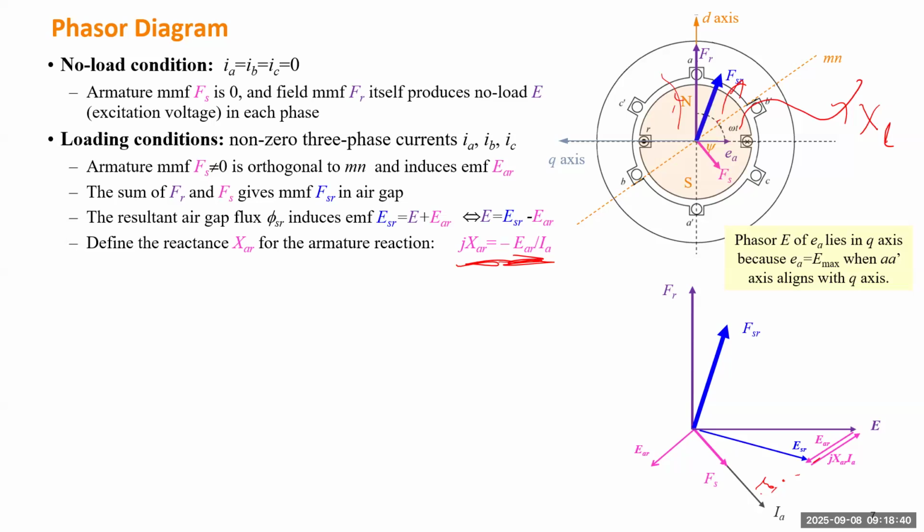Which means finally, if we connect the generator to a system, we cannot get this voltage, because this is the inside voltage, like the inside voltage of a DC battery, right? If we use the battery as an analogy, this is like the terminal voltage of an ideal generator without leakage flux, without resistance. But if it has some resistance and leakage flux, whatever voltage we get outside of the generator is not even this one, it can be even shorter.